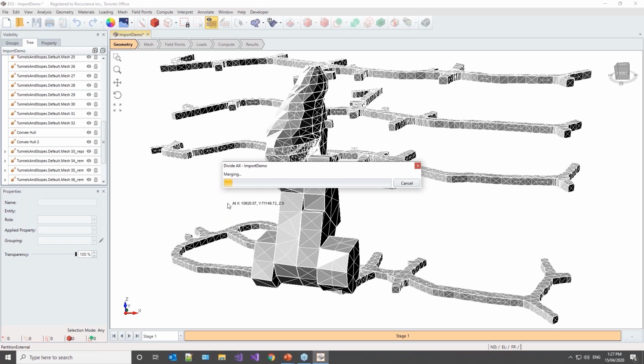This takes all the pieces of geometry that you've constructed and it forms them into distinct volumetric pieces. So if, for example, you had 2 volumes that had some overlap, instead of resulting in 2 volumes, it would result in 3, where you had the 2 pieces and then the overlap as a separate geometry. And this is critical for things like material assignments because it removes any ambiguity.